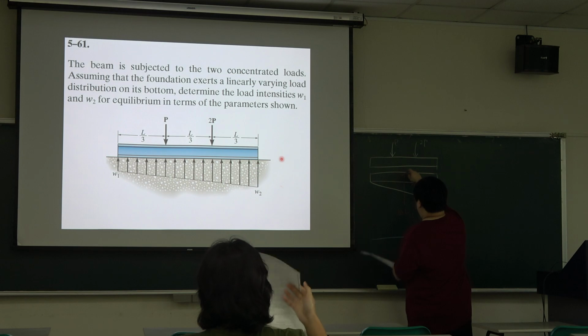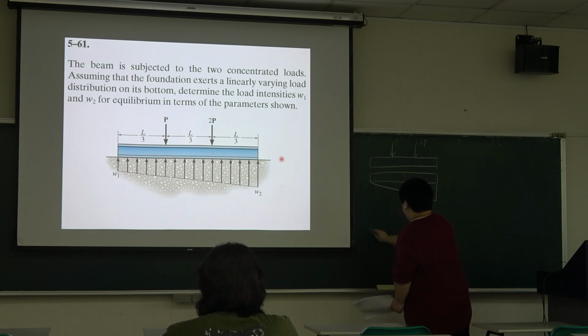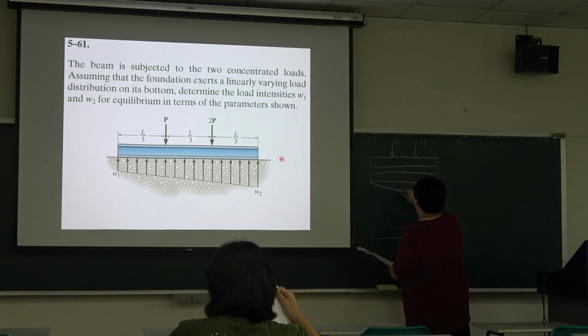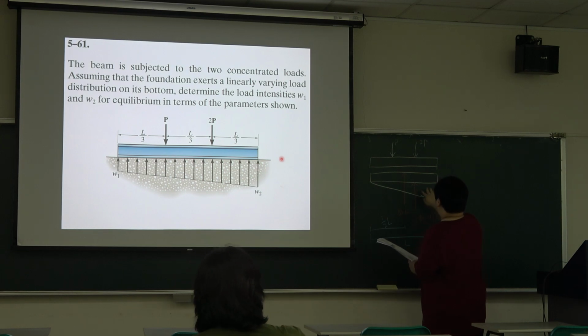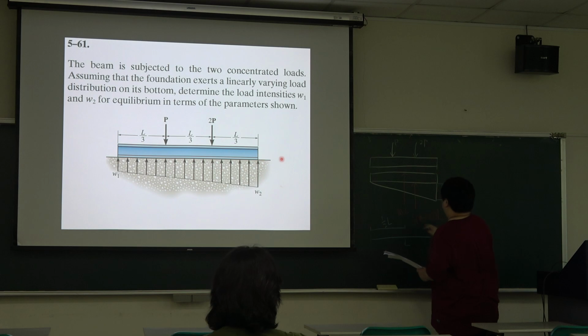And in this force, the center of gravity is at 0.5 L. And this triangle, we also have a force. The force is W2 minus W1. So the total force is just this times the L, then times the 0.5.